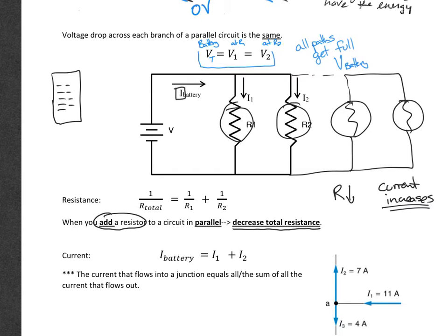And if you overload a certain room or place in your house that is all in the same circuit, some of these switches will turn off automatically, right? They get flipped. And you need to unplug those electronics, and then you go to the basement circuit breaker and reset it. Probably should do that, or have your parents do that if you overload a circuit the first time. It's not terribly dangerous, but you do need to know not to just start flipping random switches.